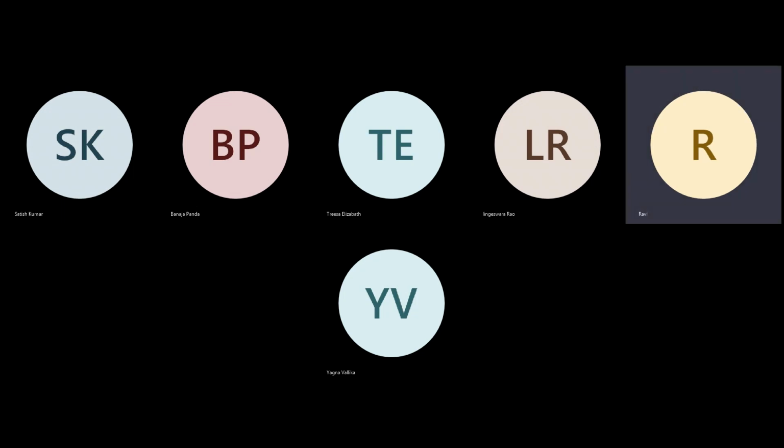See, there are two or three things. I hope you are not confused, right? One is circuit row, meaning whatever standard cell is there, that's the height. You're saying there are different heights. Yes. Okay, different standard cells. Yes. Okay, that is not possible, that's not allowed. See, it is possible to design, but it's not allowed because the current manufacturing rules do not permit it, because you will have a lot of yield losses. You can have single height, double height, triple height cells, within the same framework.